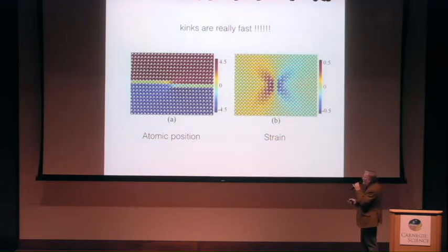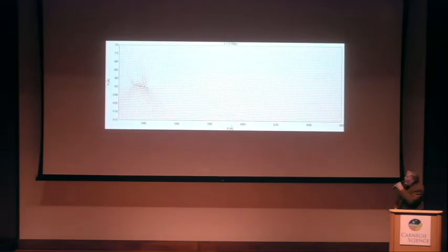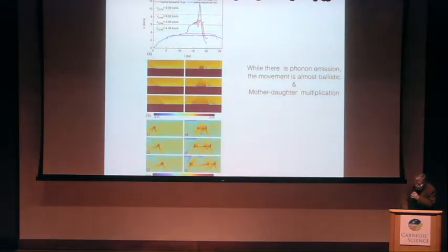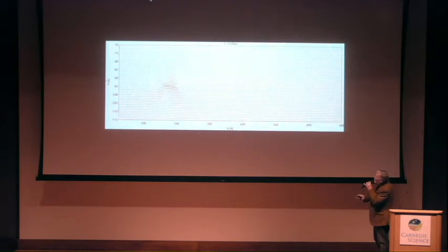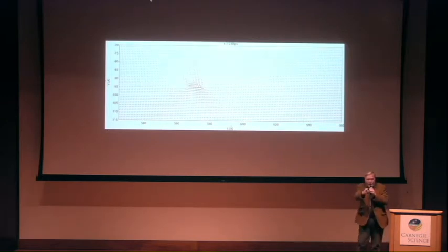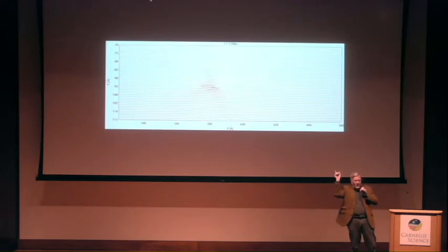So here again is the kink. This one is the Eshelby strain matrix. So that's this. It's a cross basically. And then when you look into it, here is the front. The kink is in the middle there, and it's moving forwards, and you can see this branch when it gets faster is folding backwards, and these ones are enhanced, and that's exactly the same as if you shoot a bullet and you look into the Mach cone which goes backwards, right?